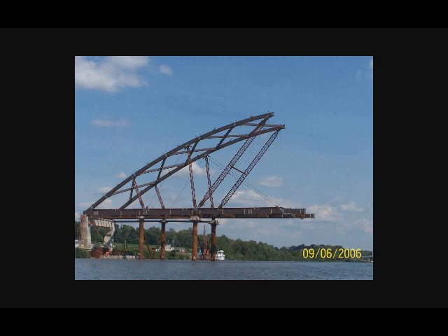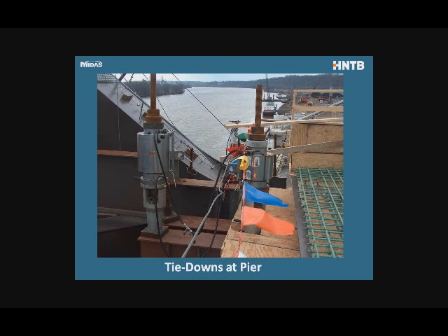So you can see a nice system. You see the arch rib supports, you see the struts that support the arch ribs, and then you can see the cables that support the cantilevering part of the tie girder. This is an interesting stage because at this stage, if you try to estimate where the center of gravity of the arch is, it's actually outside of that front line of steel casing support. So the whole arch really wants to tip over, and you have to prevent it from uplift.